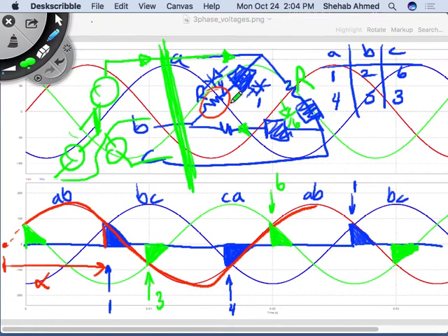This is the current inside these phases, correct? This is your concern. You're the one that has a problem with starting your motor. You want to start your motor with a lower voltage so you do not have the high starting inrush current of an induction motor. Their concern is the current that is being drawn from the utility. So I label this current flowing here IAB, this current flowing through here IBC, and the current flowing through here ICA.